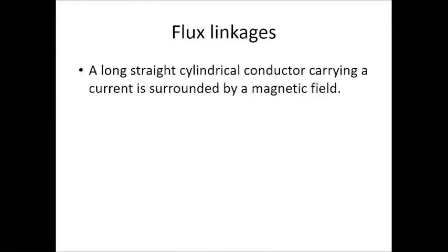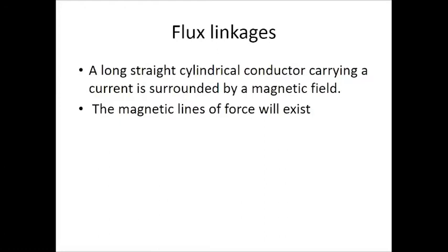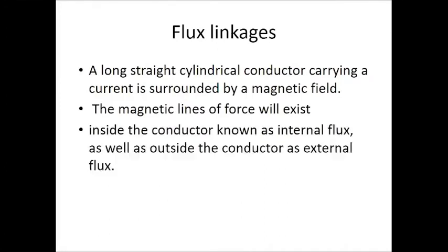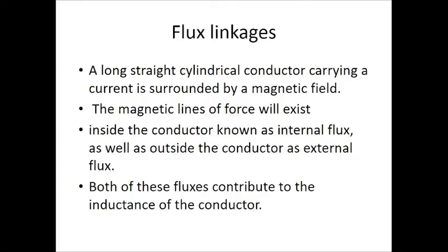Then flux linkages. So, in order to determine the inductance, we have to first determine the flux linkage. A long straight cylindrical conductor carrying current is surrounded by a magnetic field, as we have already seen. The magnetic lines of force will exist inside the conductor, which is known as internal flux, as well as outside the conductor, known as external flux. Both these fluxes contribute to the inductance of the conductor.